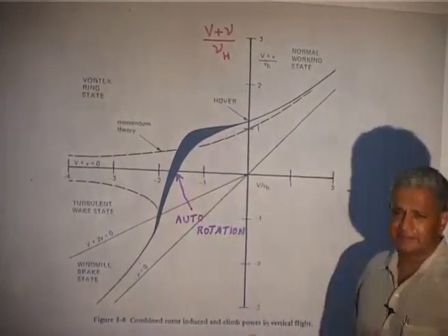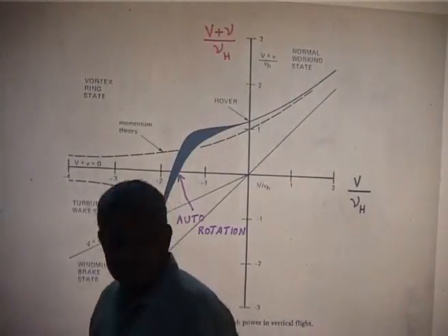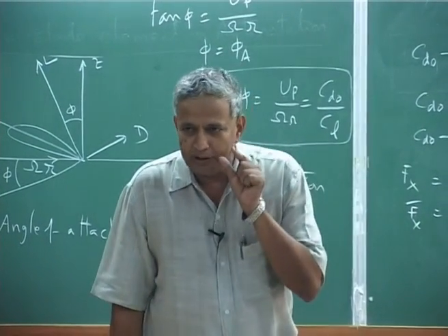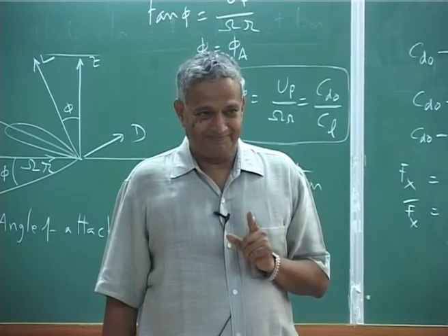This is just a dark patch. So you have to make an approximation to that line and then say that is my inflow, okay. That inflow may not be exactly at every point, you do not know what, but you have to make an assumption that my inflow is constant over the whole rotor disc, which is not true, okay. Now you see the amount of assumptions you make, which are really not correct, but still you have to get an answer. So usually the power is 0, they take it and use that condition, come to auto rotate, that is all, okay. From a mathematical point of view, it is a complex problem, okay.